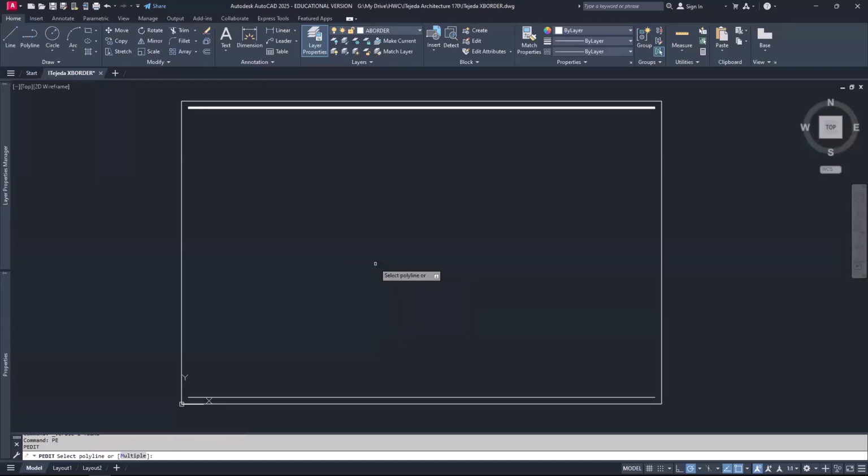Select polyline. Now, we don't have a polyline, we have a line. So you're going to select the line like this and then enter because it says, do you want to turn it into a polyline? Yes, I do. I enter. And then from here with these options, I can actually put the width in now directly. I don't have to go to my properties window. So I can type or click on width and I could say new width, 1/32 of an inch, enter.